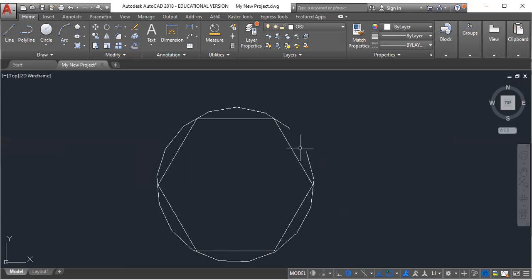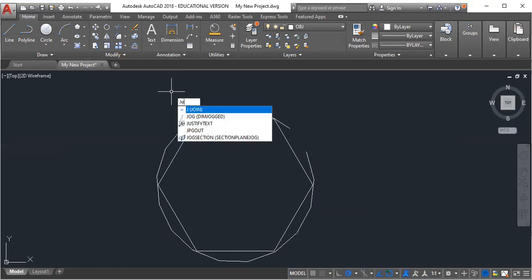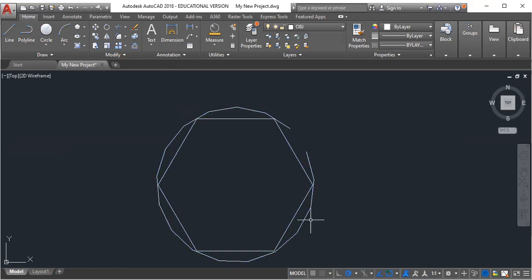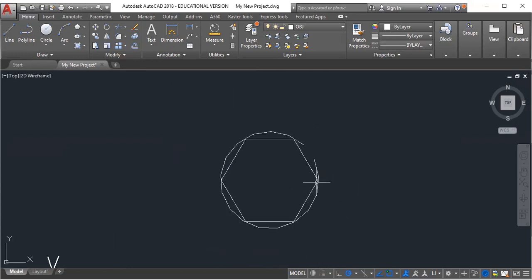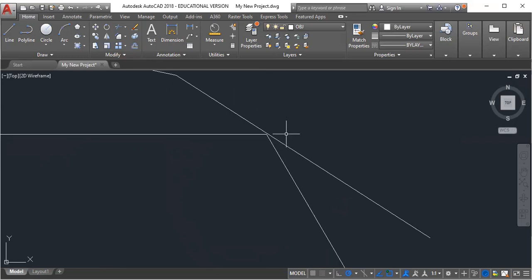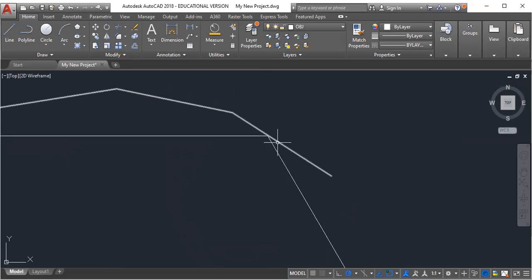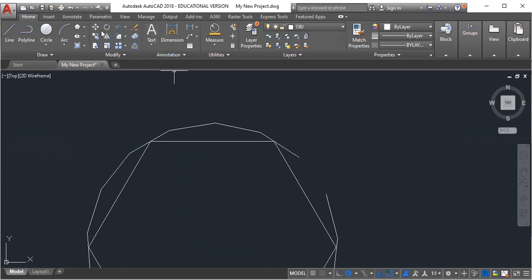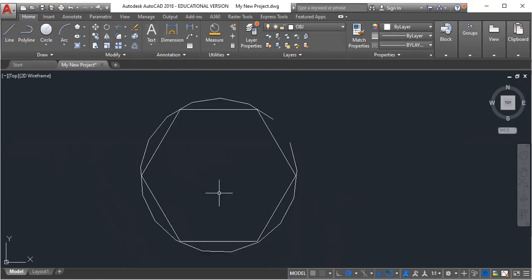and now, oh, it doesn't really join separate objects. Well, let's join them again, see what happens. This is an experiment. See if I can join these things into one. And now, do I roll over it? No, it doesn't like joining separate things. So we'll see how that works out. Because they're not touching, because we're circumscribed. Let's see. Yeah, apparently the objects do need to be touching for join to work. But join and explode still work the same way with polygons, and that's the important thing.